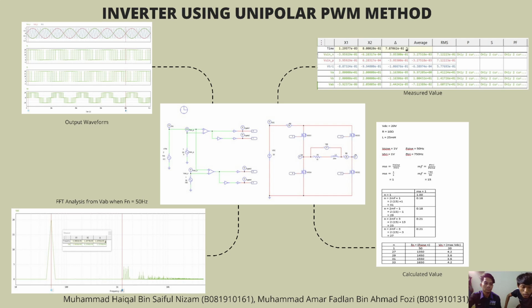Normally switching circuits tend to have lower power consumption because the switching devices are always either fully off or fully on. Furthermore, PWM signals are quite easy to generate. And lastly, the PWM signal can be used to accomplish digital to analog conversion. So the right circuit is the unipolar inverter circuit that will be controlled by the PWM circuit.